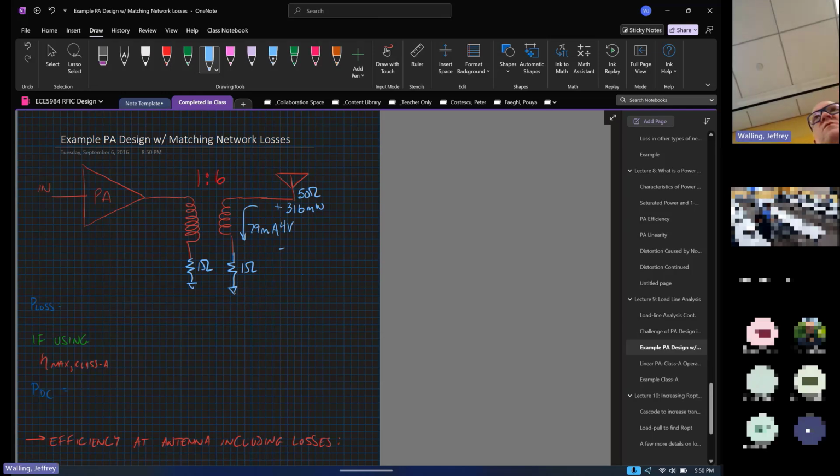We're doing a 6-to-1 impedance transformation, and so we're going to step the current up on the other side of this. So we're going to have more current over here. In fact, about 474 milliamps, but the voltage swing is going to be about 0.67 volts.